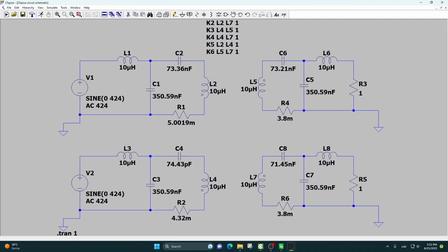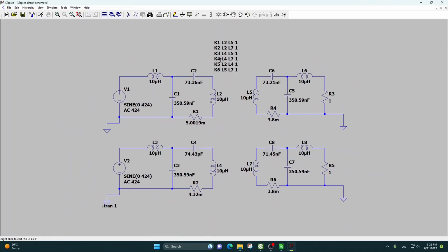In the same way, I would also suggest to define coupling coefficients between every two coils. Here I have very arbitrarily defined perfect coupling between every two coils. You can of course change the values, and you can choose not to define them at all, in which case CENOS will predefine them. But again, if you manage to define coupling coefficients between coils more accurately already at the beginning, then the convergence will simply take less time.